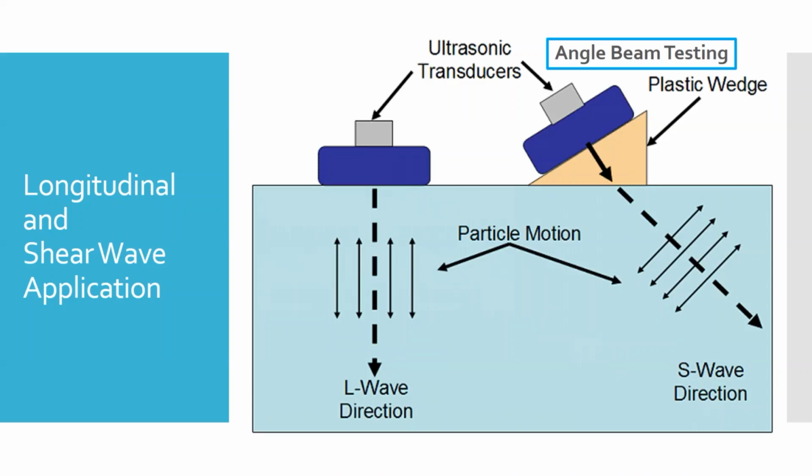So we send a pulse into a material, it travels through the material till it hits some kind of an acoustic barrier. In this case, it's the back surface of the object, and then would bounce back up. And that's going to be primarily those longitudinal waves. That's that, the molecules here are pushing against the next row or pushing against the next row, right?